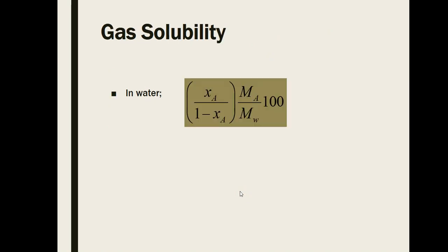Now, there are equations already shared with you in phase equilibria that we can make use of together with material and energy balances in problems concerning gas absorption and stripping. This particular equation now shown on your screen allows you to determine the solubility of any gas in water. This is available in your handbook. What is good about this formula is you only need to know the mole fraction in the liquid phase of a particular gas to know its solubility. This is only applicable for solvent water.